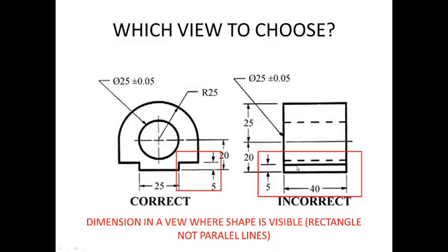All you have is two parallel lines and you're not really sure what's going on there. Is it a radius or is it two parallel planes? And the same stands for dimension R25 here. Or there's another reason why you wouldn't put a diameter inside of here, because you should never dimension lines like this. If you see something like this, either you would cut it out and then dimension this diameter in the section view, or you would do exactly what it's done here in this drawing.